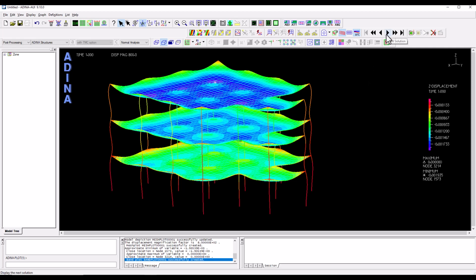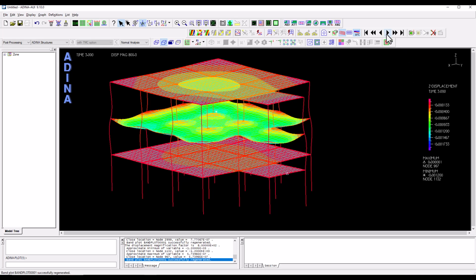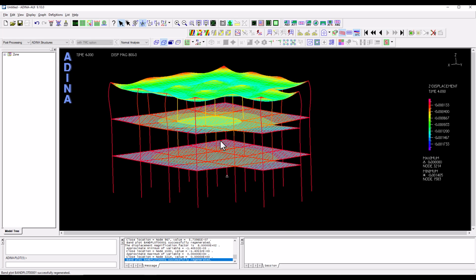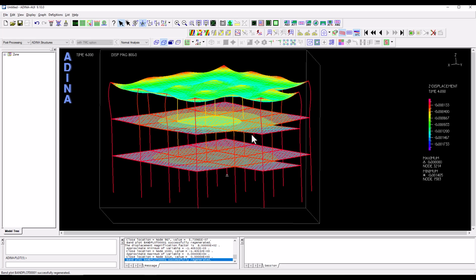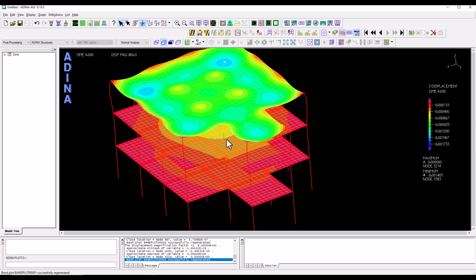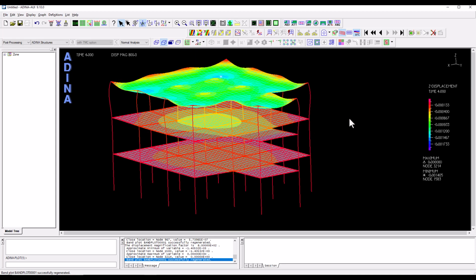So we can go through different load cases. We have 1 millimeter, 1.2 millimeters, and 1.4 millimeters. It makes sense that where the load is highest, we have more displacement, but all looks fairly sensible and symmetric. The next thing is to look at internal forces on beams and shells, at least qualitatively.